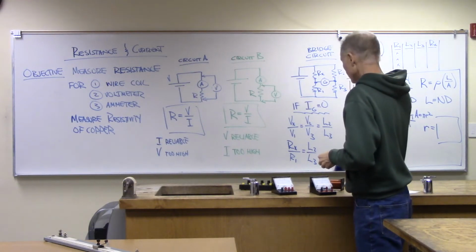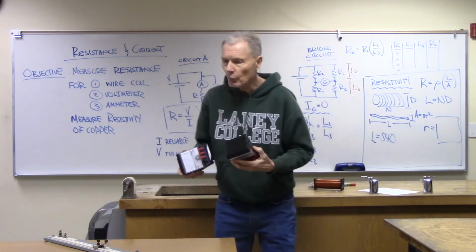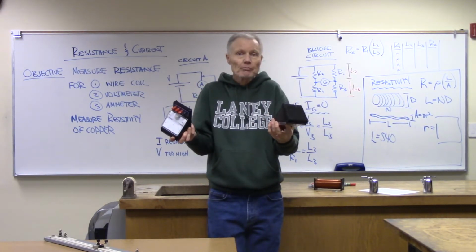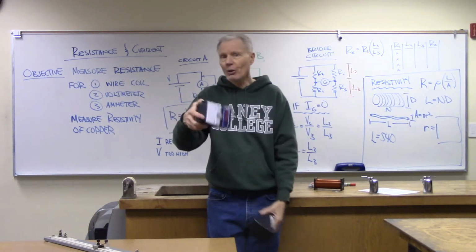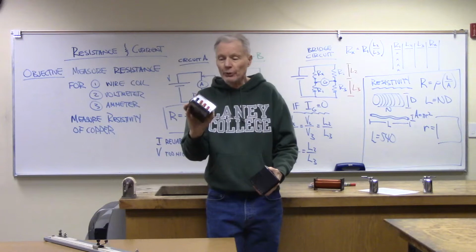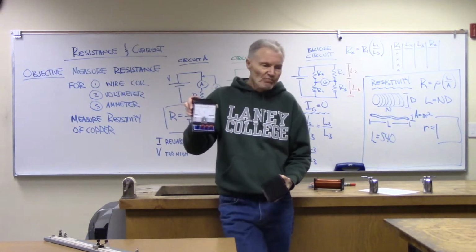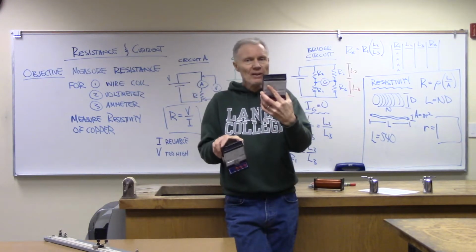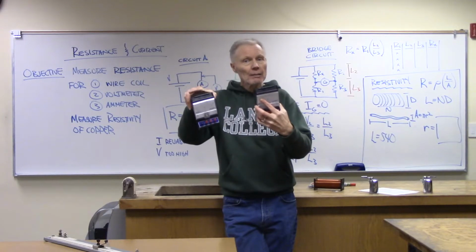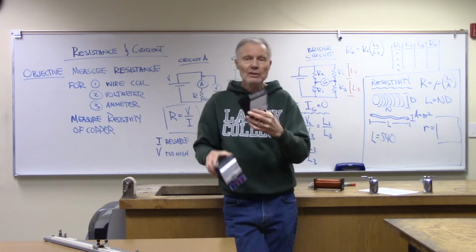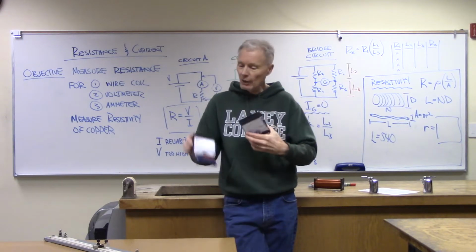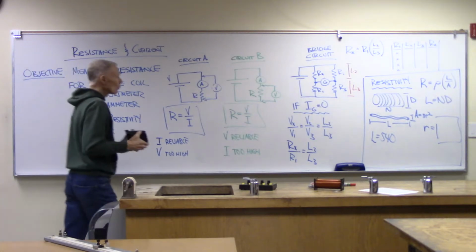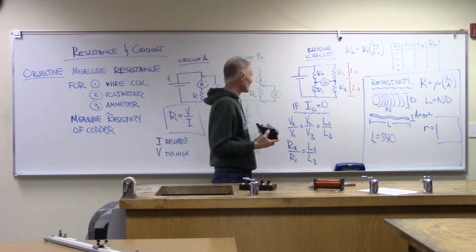With the bridge circuit, what we can also do is bring back in these voltmeters and ammeters and find out how much resistance they have in them. Remember we talked about this: it's just a resistor with a magnetic loop of wires moving our needle. Same thing here. So we could actually measure how much resistance there is in these two devices. The ammeter we're guessing is going to come in really low. The voltmeter is going to come in really high. We'll find out if that really works the way that we imagine that it does.